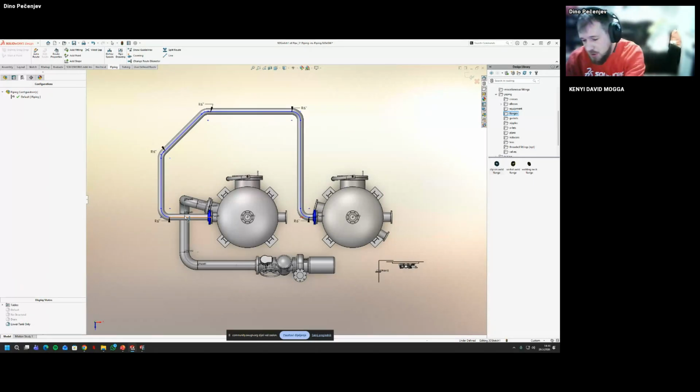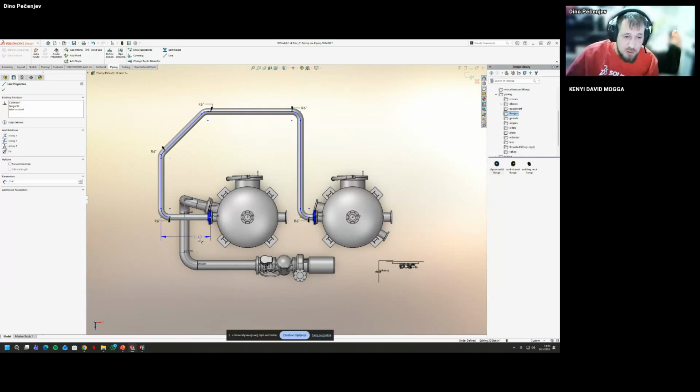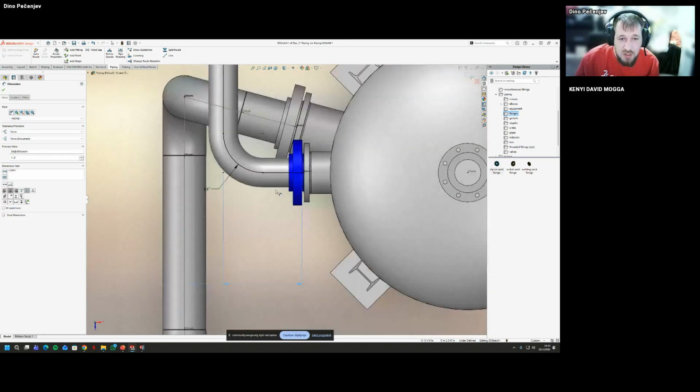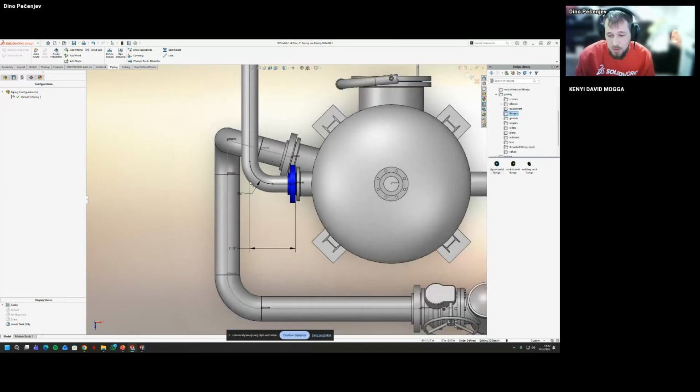So for here, I'm just going to use some specific dimensions regarding this. So I'm just going to dimension. And if you notice that in routing, when I'm creating the dimension, this is going to be 1 feet. It's actually using the whole length of this section. That's why we set the option to use center line. So it goes from the start and right at the crossing of the two intersection of the two lines. So I don't have to deal with pressing where to here. No, it's just going to do the whole section of this.